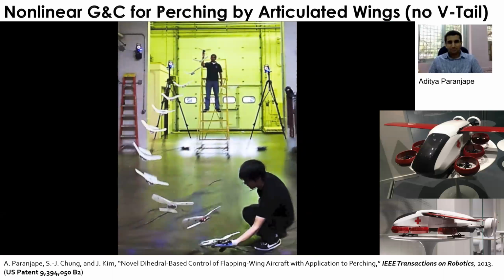I want to also take this opportunity to talk a little bit about some of the research activity. We are actively working on the flying car, flying ambulance. What's new here is that instead of a single rotor or a big gigantic rotor like a helicopter, we have distributed electric propulsion. Here we have 8 propellers, and we also have a wing, which means you can fly a longer distance because you don't have to use just the propellers to move forward. You get lift out of the wing once you have sufficient flight speed. And it poses unique control challenges.